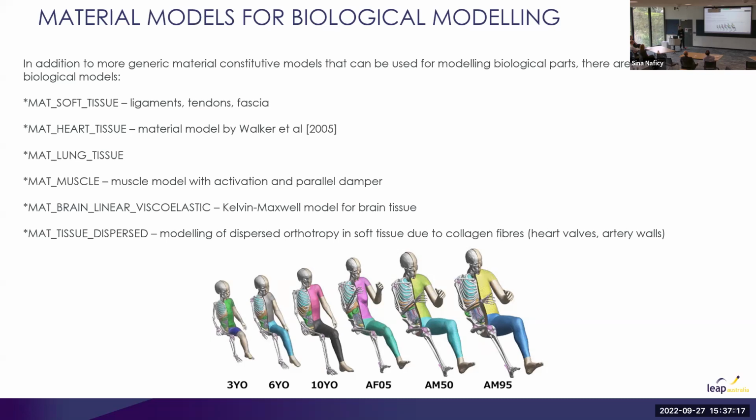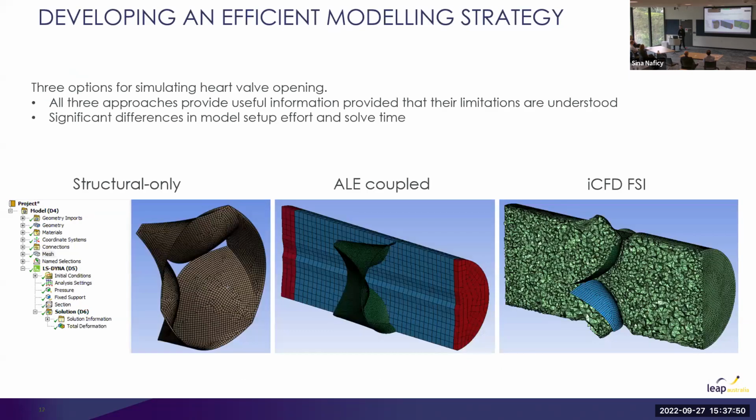And what you see down here is the Toyota THUMS model, which is a dummy model developed by Toyota for crash simulation. And it's an improvement on the Hybrid III dummies that have been used traditionally, which are basically simulation models of Hybrid III dummies, whereas this is a simulation model of an actual human. So you can see all the various bits of tissue and bone and everything like that. So you can have injury criteria based on the state of the lungs and the heart and the brain and all that sort of stuff. So they're very clever and sophisticated.